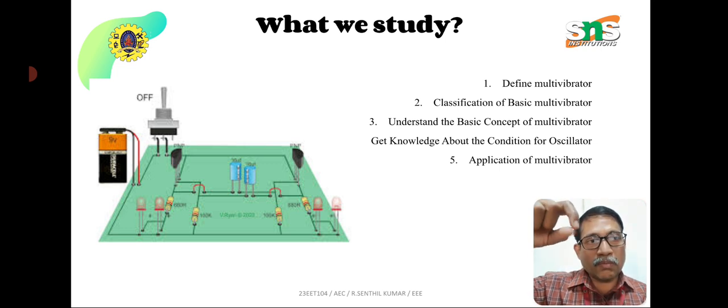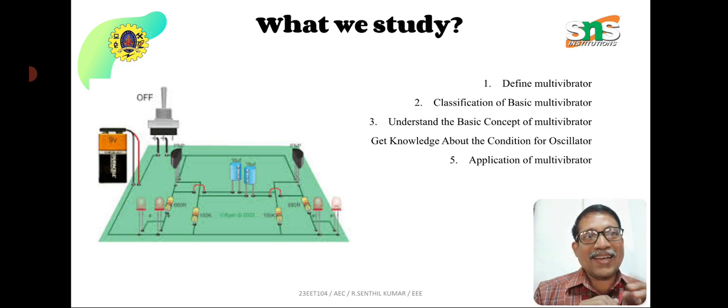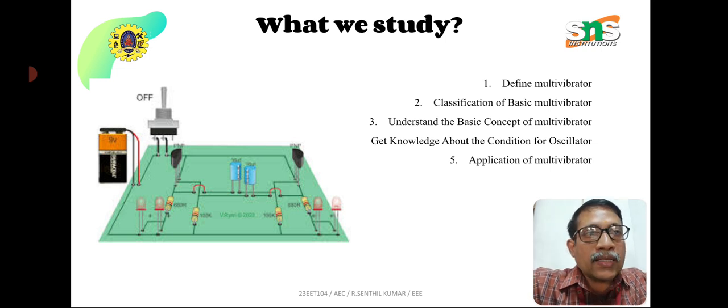and the left top is nothing but the potential divider. Simply to say, it is a pot. And the two black ones at the extreme end are transistors. Therefore, in general, a multivibrator circuit consists of 4 resistors, 2 LEDs for output, 2 transistors, 2 capacitors, 1 source, which is a battery, and a potentiometer. The 2 transistors are acting in active and saturation region, you mean acting as a switch.